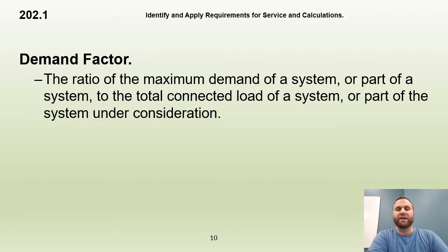Now, before we get into sizing the service for a single family dwelling unit, we need to talk about a term that's going to be brought up quite often when discussing calculation methods, and that term is demand factor. The NEC definition for demand factor is what's written here. It's the ratio of the maximum demand of a system or part of a system to the total connected load of a system or part of the system under consideration.